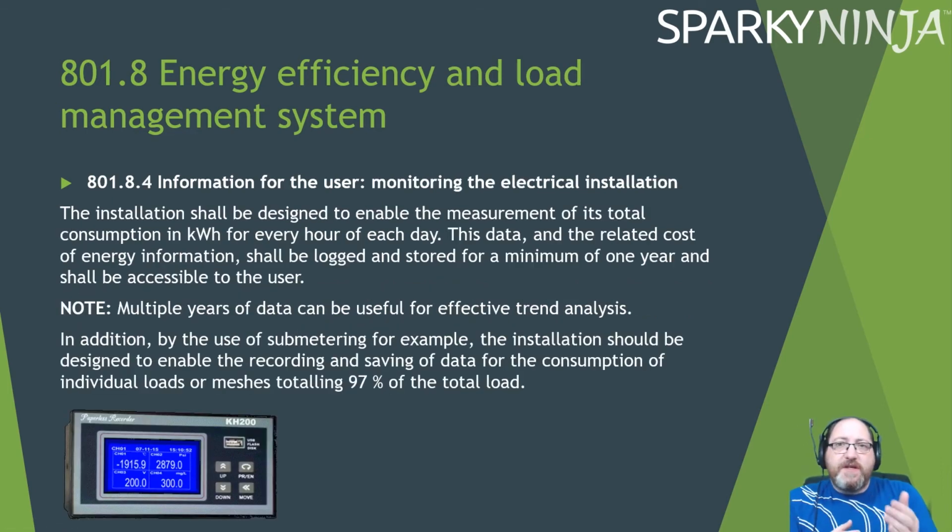Monitoring. The installation should be designed to enable the measurement of its total consumption in kilowatt hours for every hour of each day. This data and the related cost of energy information should be logged and stored for a minimum of 1 year and shall be accessible to the user. Again, for a user to make decisions, they've got to have data.